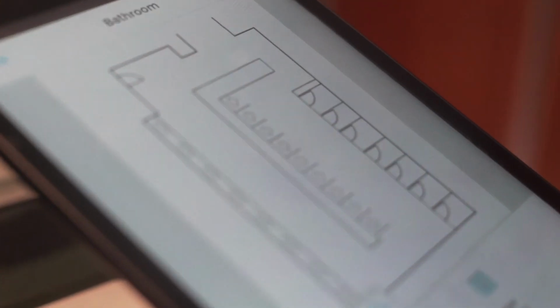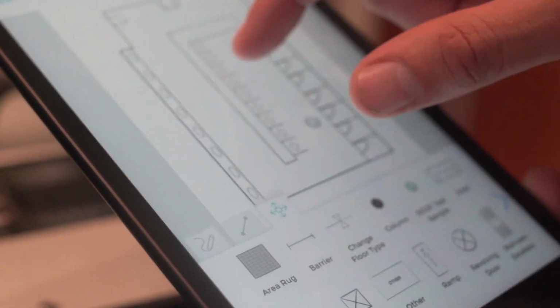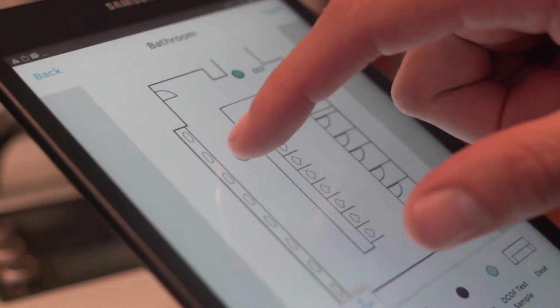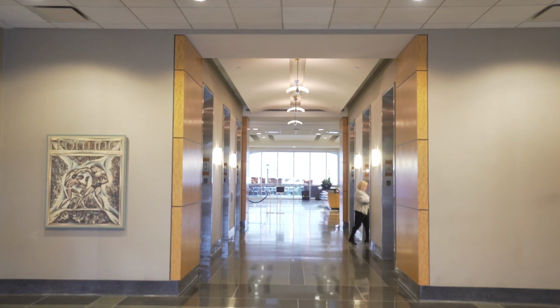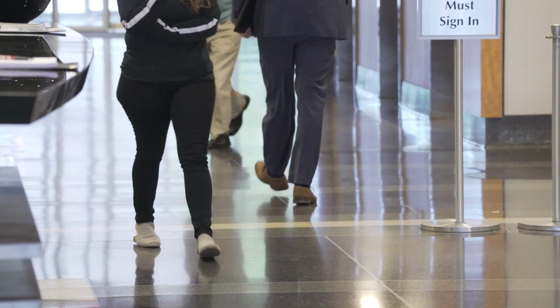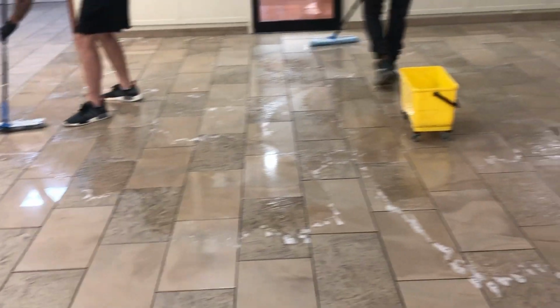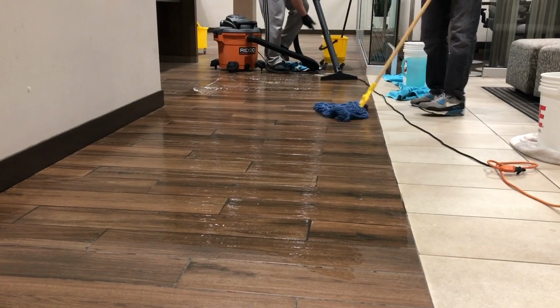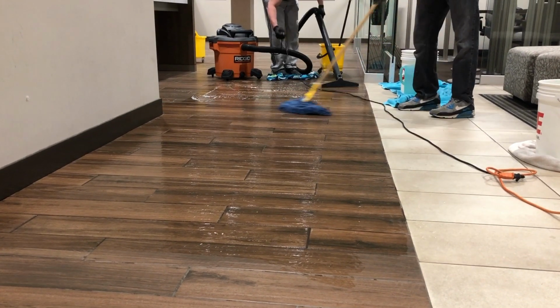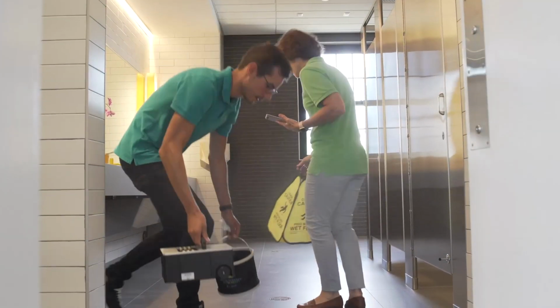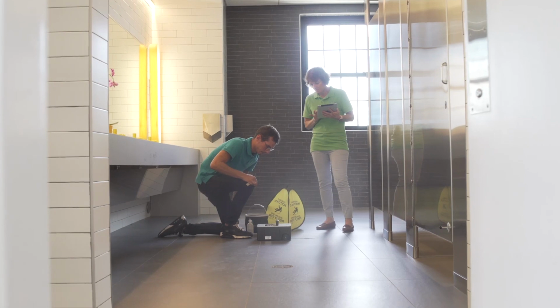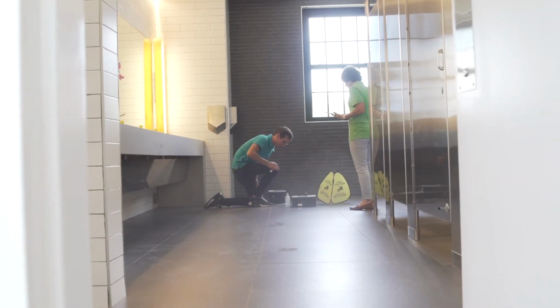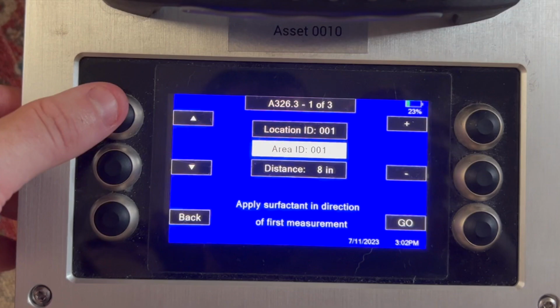Next, determine specific DCOF test locations within your test area based on the test objective. Note, test locations should include samples of both high and low traffic, materials of different sizes or textures, and materials commonly exposed to contaminants or other risks. Each test location must include 3 test samples. Keep in mind that the travel distance of your BOT 3000E should be set to 8 inches.